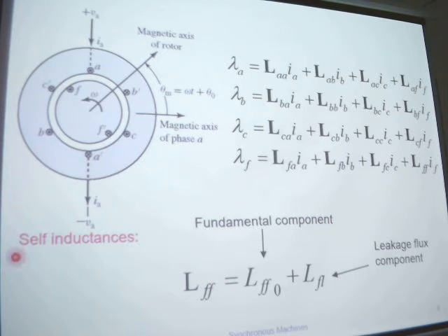First we see the self-inductance L_FF, the rotor self-inductance. L_FF is equal to L_FF0 plus L_FL. L_FL is the leakage flux component.